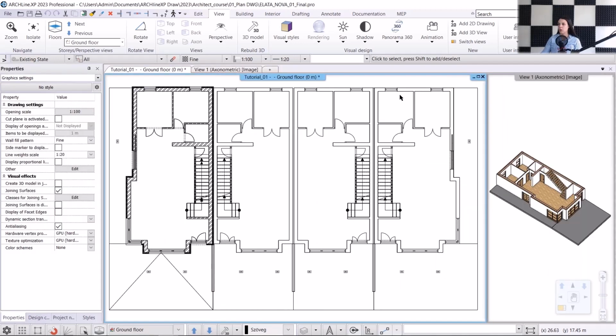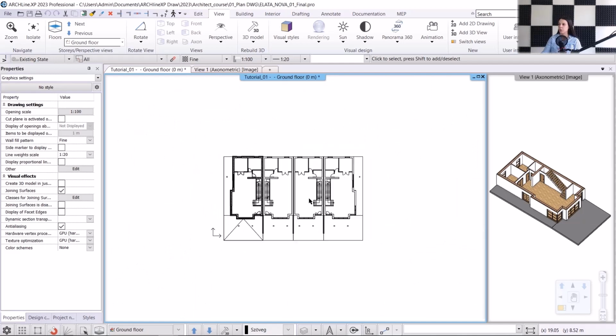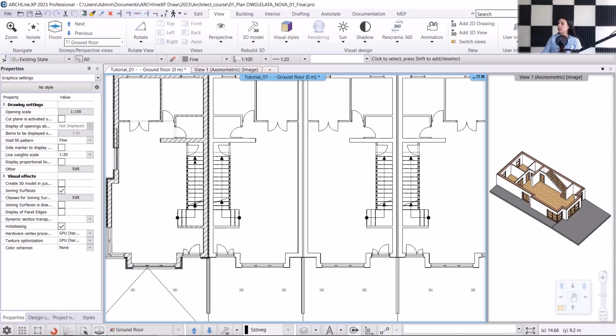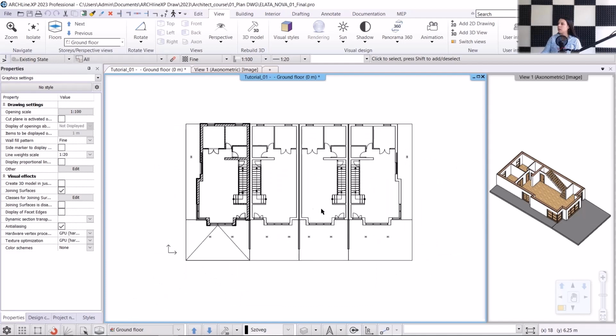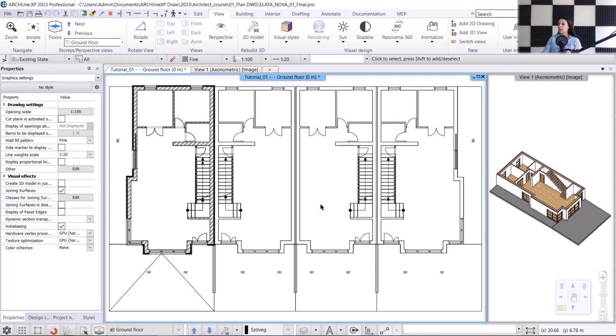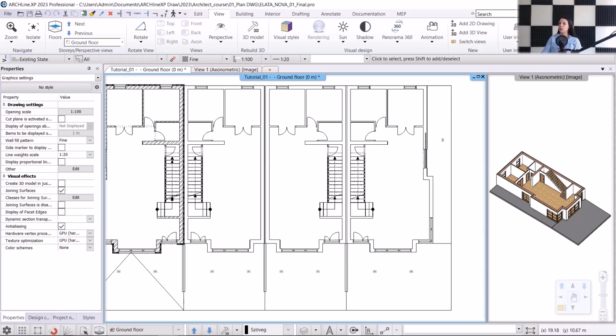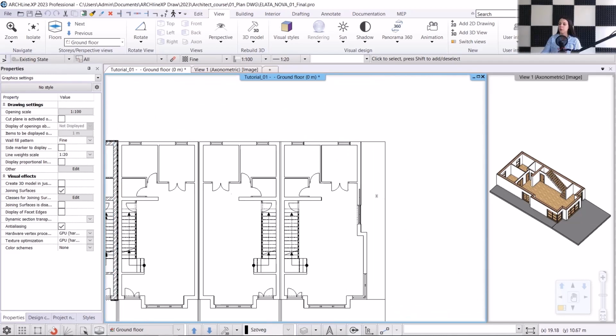Now, let's see how to navigate between 2D and 3D views in the program. We can zoom in and out using the mouse scroll wheel. If we have zoomed too far out or too far into our floor plan, double-clicking the scroll wheel will reset the optimal zoom level. To move around the floor plan, we can press and hold the scroll wheel, making navigation easy.